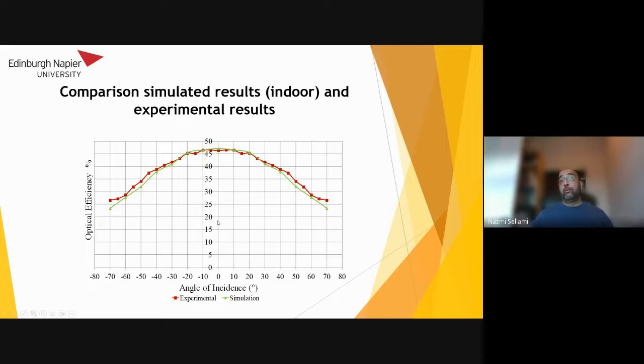You might say it's a low efficiency, yes, but again, we have the advantage here that we are using surfaces that haven't been used before, which are windows. We have increased the transparency of this window, and also we are not using any tracker. And by using the concentration, and we have a concentration of 4, so with the 50 or 45%, we can have a concentration of around 2, covering pretty much the whole day. Here we can see the angle of incidence, and from there we can refer to the time of the day. So these are the results of our experiment.